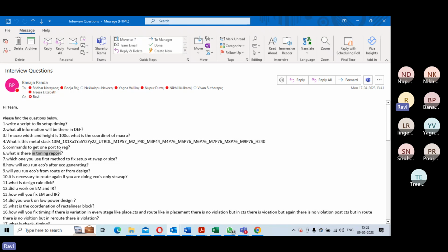You get start point, end point, slack, which delay type. There are all the cell and nets in that data path. Whether it is violated, you can even get the information of crosstalk like delta delay, and variance. Each cell can get the delay information.